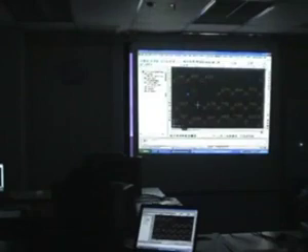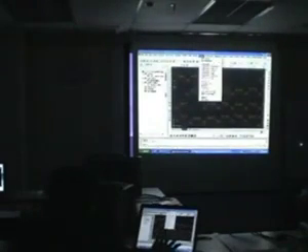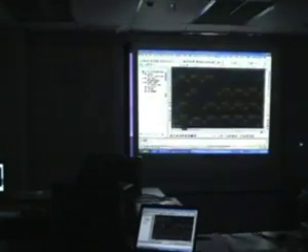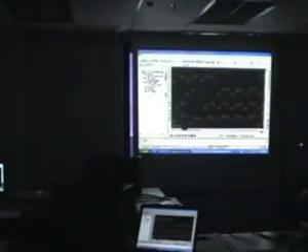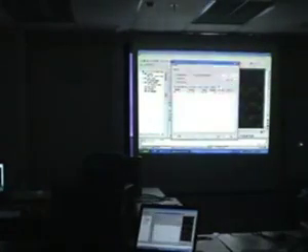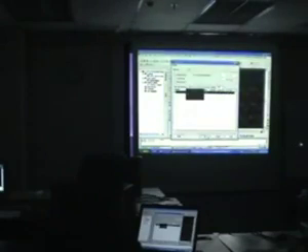Let's say, for example, the surveyor goes to the field and indicates that at this particular point there's a tree, or a drain, or road line, wall. You can attach that kind of information in here as well. So at least you're not just looking at points without knowing what they represent. Just to give you an example, I'm going to edit this point and write here, okay, there's a tree. So I'm just going to write tree. Click OK. You can see how the word tree automatically appears.